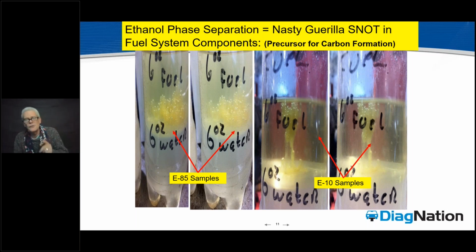This goes right back to drive cycle, and not only the heat and carbon burning out of the engine, but how much of it is being made. Because if you're a short tripper, you might have that gasoline in your tank 2-3 weeks before you fill up. That car is getting decked with that deposit. We need to understand it, treat for it, know about it, and then put baseline theory together to go look for it in our scan data and help get it out of the car. But that is the significant visual that you need to see to understand the drive cycle aspect of it, in addition to the heat of the engine.